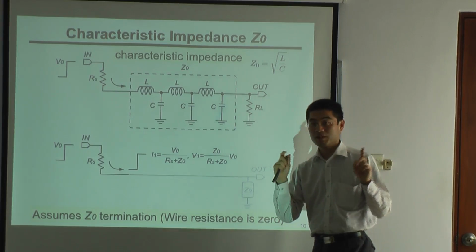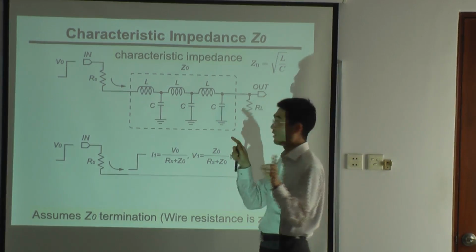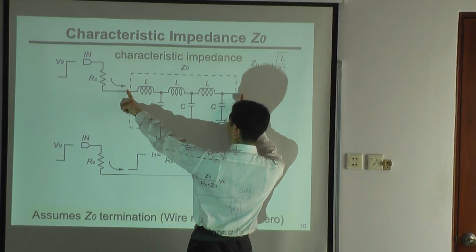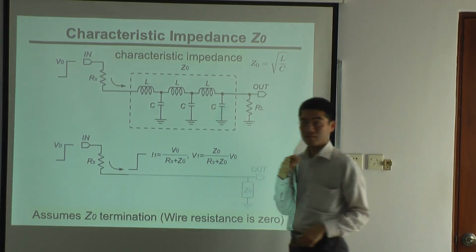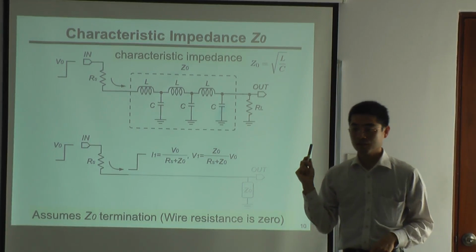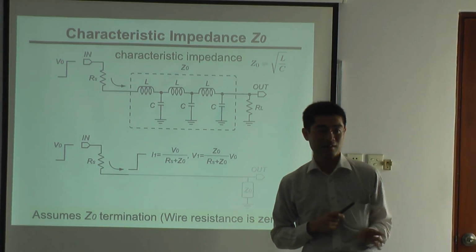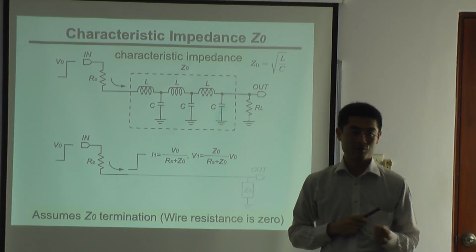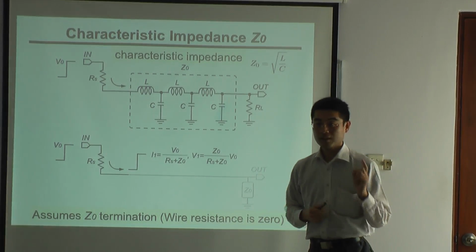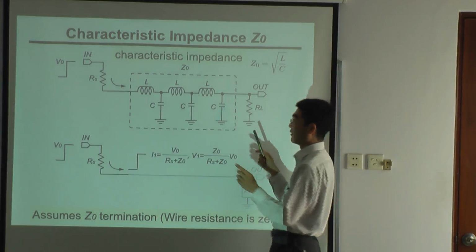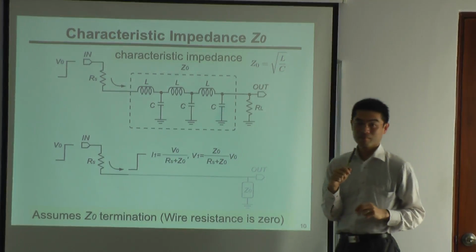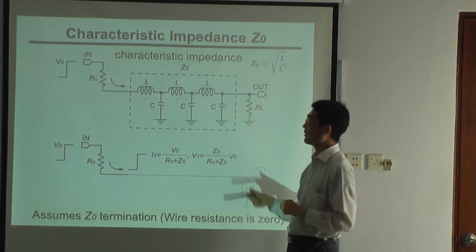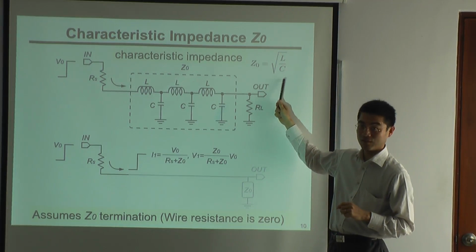But when we measure a resistance with digital testers like here and here, the digital tester says this is 0. So here we have to consider DC resistance and AC resistance. For DC resistance, it sees only resistance. And for AC, it sees this one.